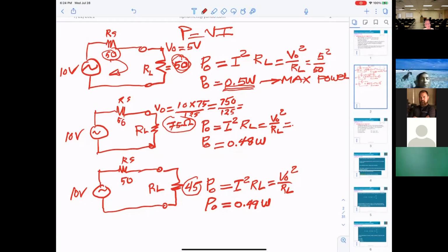So that's why when you see the generator output, they put 50 ohm, right? That means the output of the generator will be 50 ohm. So there is a coax cable that will have the 50 ohm resistance, so you can get the maximum power from the generator.